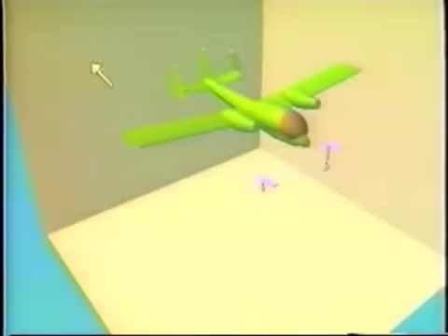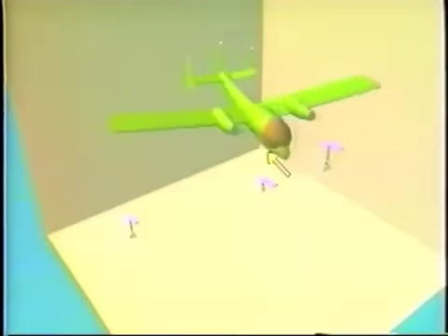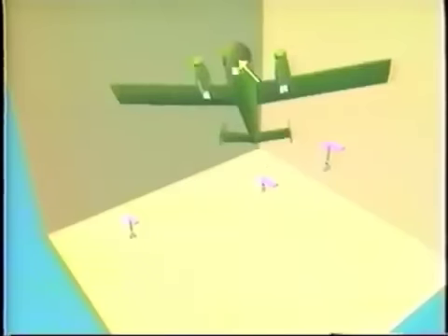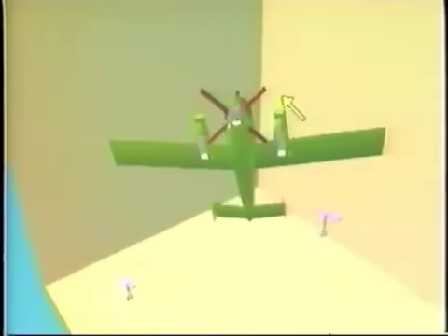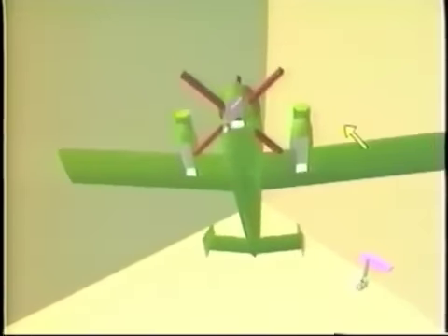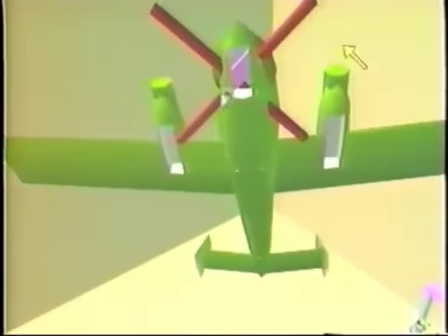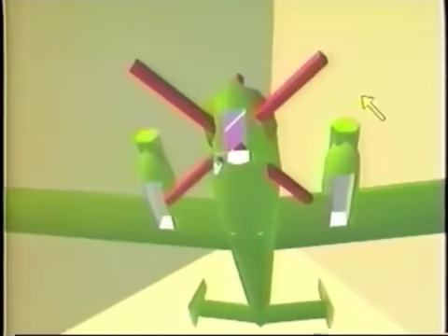Another way to achieve the same snapping effect is to rotate one of the objects so that both snapping surfaces are visible. The user rotates the plane so that the destination surface can be seen, then a point on the landing gear is selected, and a snap to the now visible underside of the plane. Since we had to modify our model, the invariants required by our naive implementation of snapping have been broken, and the landing gear is misaligned.